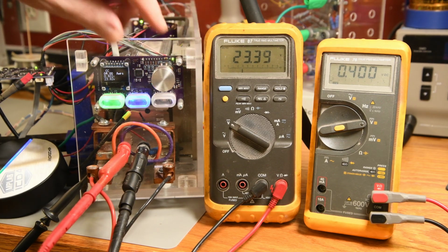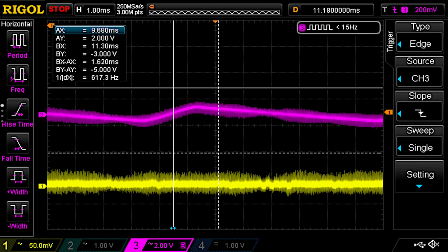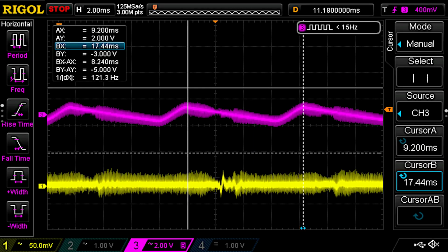Now by the time I get to 4 amps, the 45 kHz oscillations have stopped. They seem to drop out by 3.5 to 4 amps. I'm now pulling enough current to really see the 120 cycle ripple in the voltage waveform, and another very good view of the fan noise making its way into the 3.3 volt supply. The small amount of high frequency noise on both waveforms is not the 45 kHz oscillation. It is the 125 kHz switching spikes from the power supply.